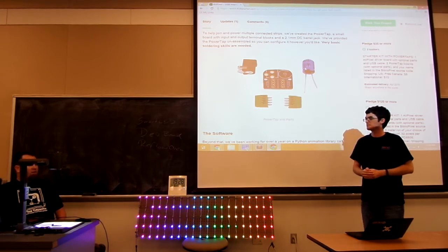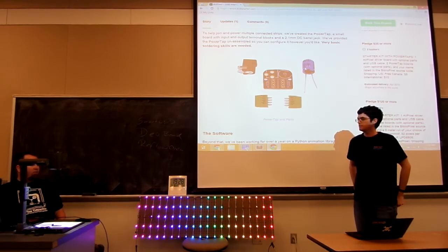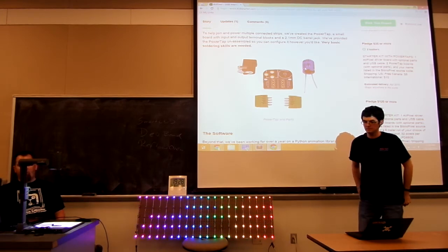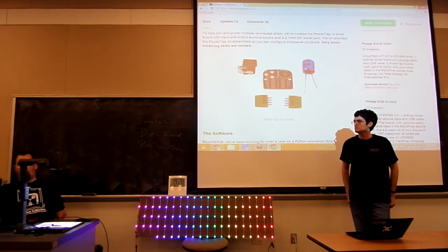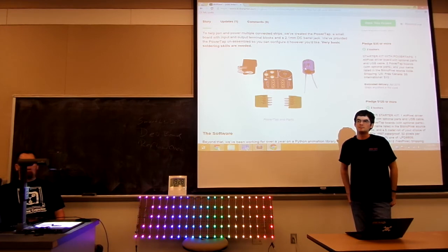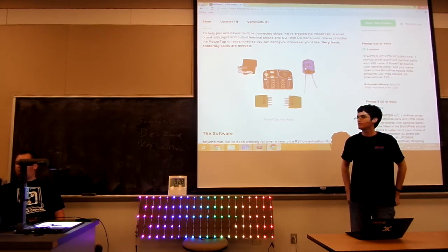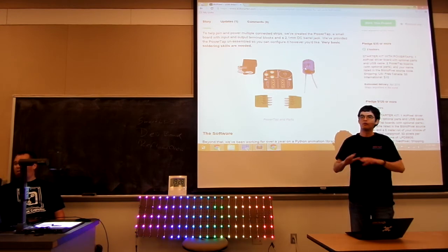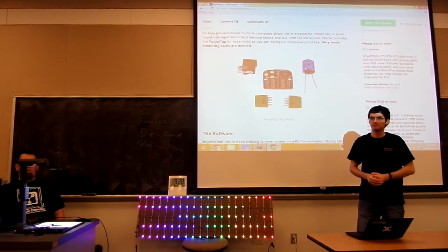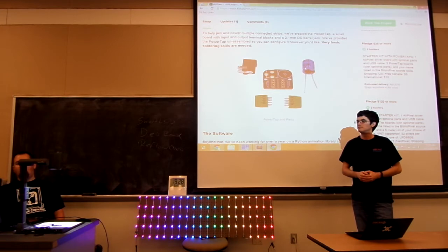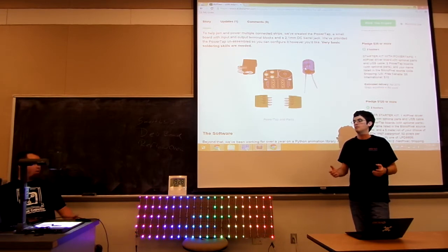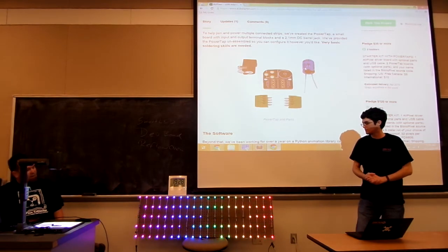And as we found with these, I've played with enough of these LED strips that, for example, a 5-meter roll of the LPD at 30 pixels per meter will claim that it's going to draw 12 amps. If you look at the math, it's 60 milliamps per pixel or 20 milliamps per color at full light, full white, full intensity. It will, but it never does. And also with this, it's only ever kind of half on.